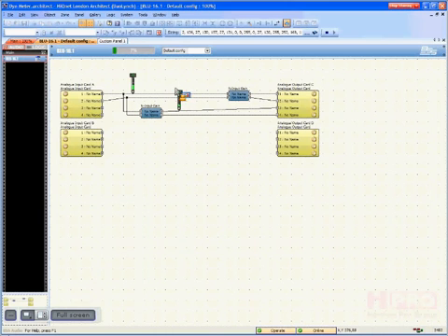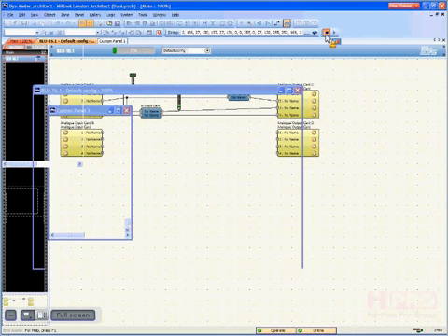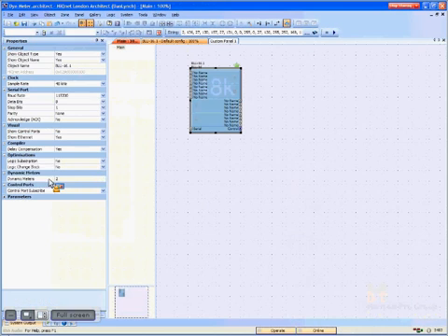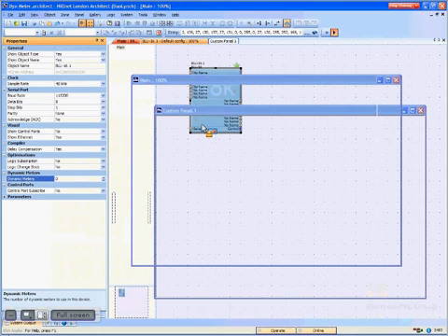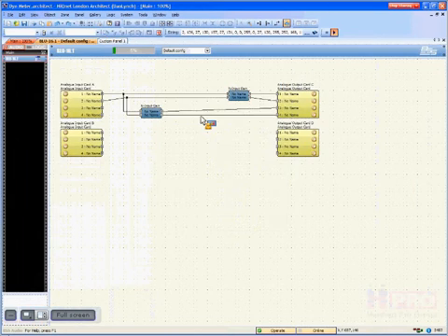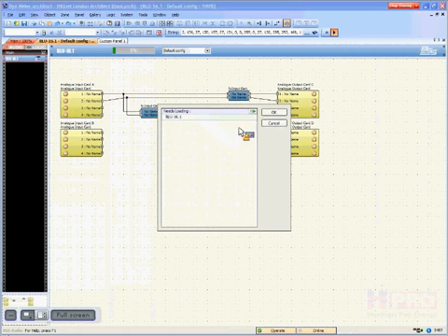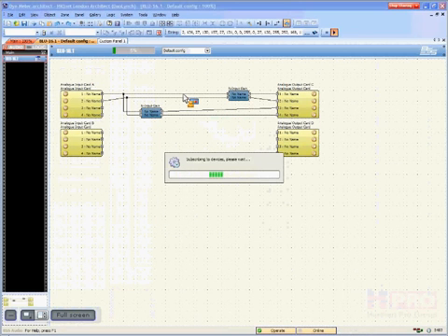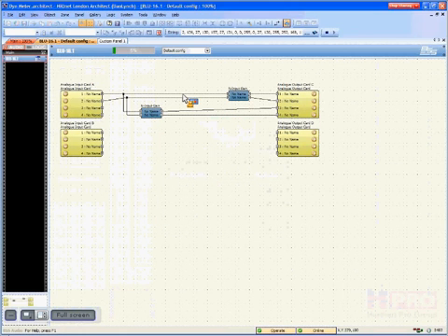So you can save some DSP power by not cranking those up. Again, they'll default to 2. They won't default to 20. Not quite that stupid. And if you're not going to use them, if you're just scrapping for every last little bit of DSP power, you can always turn it off. You see our DSP power has dropped down to 5%. The only thing is, once it's up and running, if I hover over that wire, nothing happens.